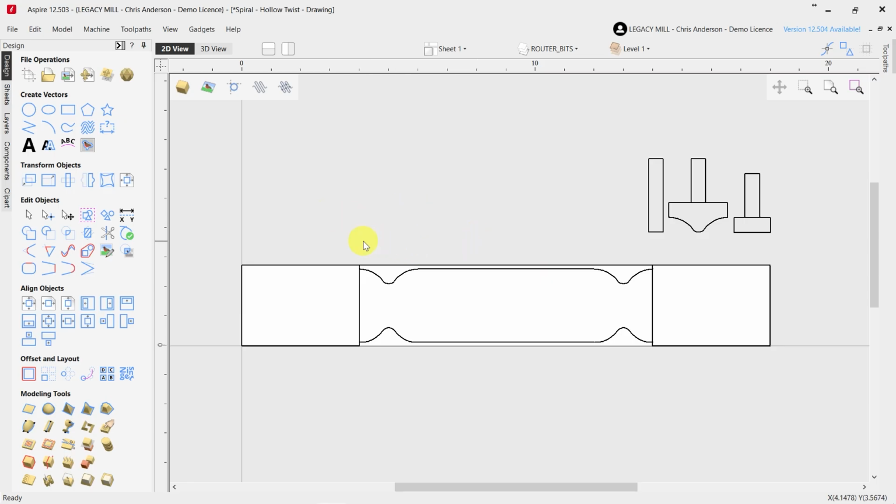Just like other spindles we've done in the turning round sequences where the stock is in a round shape, this is going to be no different. We have a square section on the left side and a square section on the right side of this design, but the middle section is all going to be turned. The spiraling process is going to be applied to this turned section. This has already been toolpathed and programmed. We used a surfacing cutter to turn that entire stock round to 2.5 inches in diameter all the way to the end. We also used this 2-inch barley twist cutter, and this cut the tool profiles here at one end and another one here at the other.